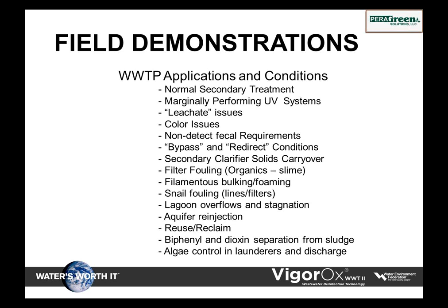Another thing we've looked at recently is bypass and redirect conditions. Some of these facilities don't have the ability to hold water, so they have to bypass the plant, or in New Jersey, they call it redirect. At that point, we actually bypass and redirect around the secondaries and filtration and UV. The tests we've conducted, we can handle that discharge and still maintain compliance. We've also seen secondary clarifier solids carryover. I'll show you 2 charts later that demonstrate this and what the forgiveness of PAA is.